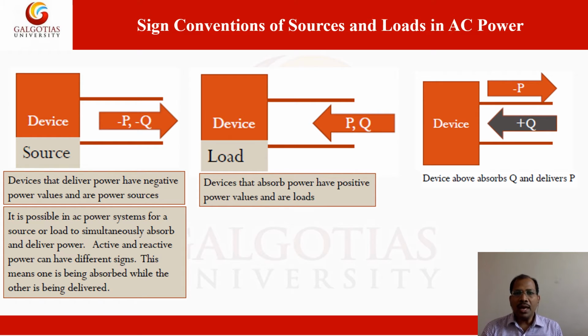These P and Q are the powers injected by the generator into the grid. So we consider this as the negative, because there is power injection into the grid or the bus. And suppose a bus is there and we have to take some power, or the power is absorbed by the load. This power we consider with a positive sign.